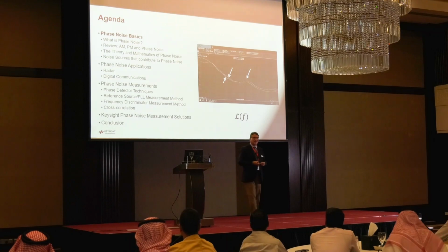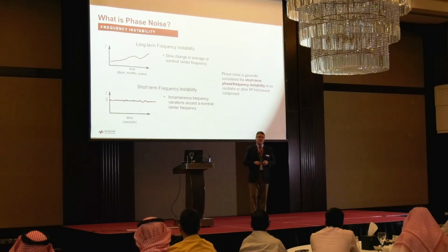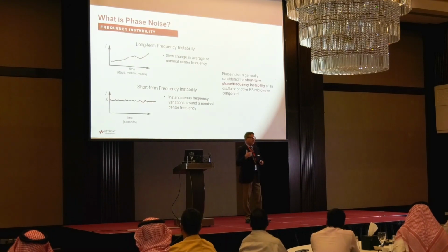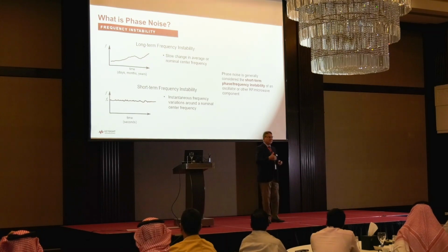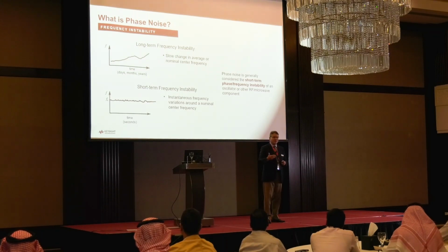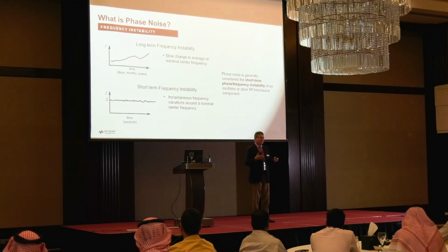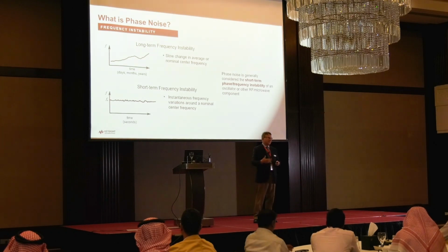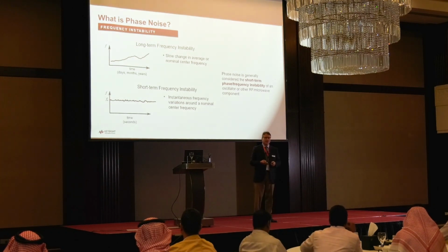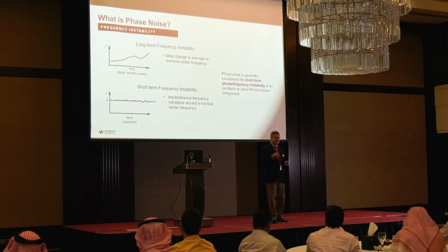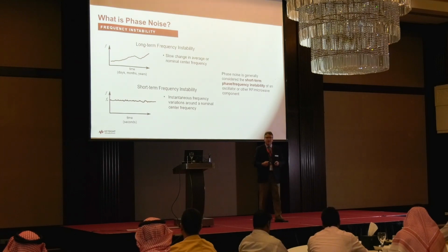So let me start first by talking about what is phase noise. If you look at any kind of a signal, a carrier of information, it has a frequency, right? Whatever it might be. It could be 100 megahertz if you're tuning to an FM radio. In cellular, it might be a gigahertz or 2 gigahertz. And we generally make the assumption that that frequency is constant. It may have some modulation on it to carry the information we care about.